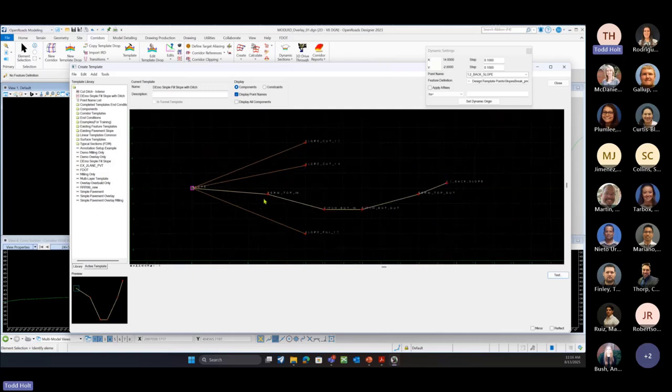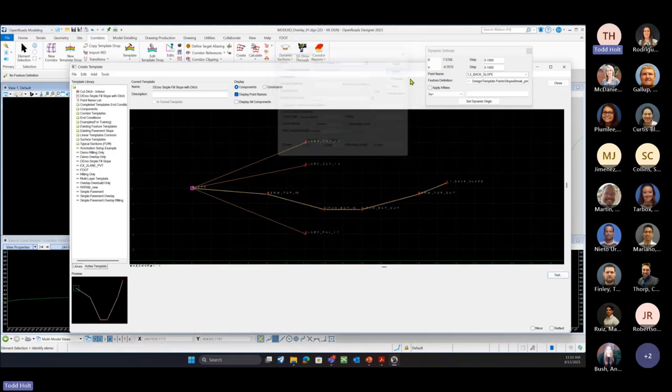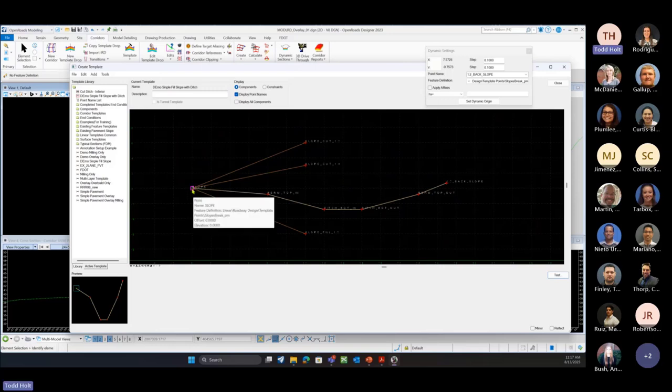All right, so there we've looked at our component properties. We still have one more where we're going to target a right-of-way line. So we're going to build that, and not in the next exercise, but we'll get to that. So the next one that we're going to do is we're going to build a constant width, but a varying slope clear zone. So maybe we know what the width is from our tie-in point, but we want to have a variable slope that we're going to build in.